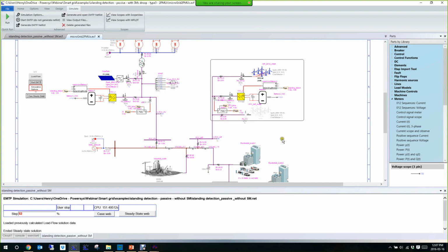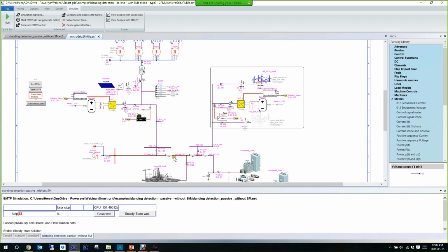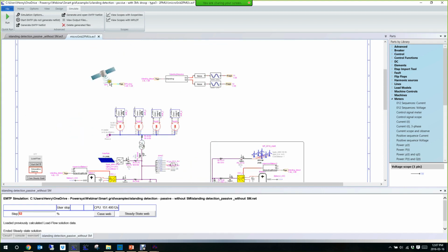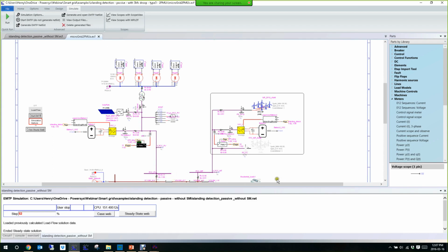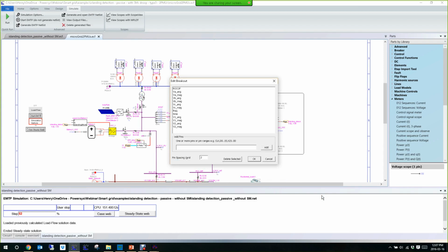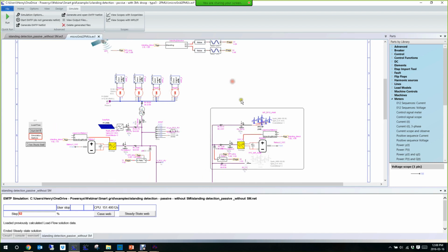Okay, so here what we do, we have the PMU. I improved a little bit their model, and I synchronized them with the GPS. Okay, we have a satellite here that gives the time, and the satellite synchronizes all PMUs. And so now, again, I modified a little bit the PMU. Now the information they give to the islanding detection are these ones. The rate of change of the frequency, the voltage magnitude and angle, the frequency, the positive negative sequence, and the time. Okay, and so that's important. Now we have the time. And they send like that these threads of signal.